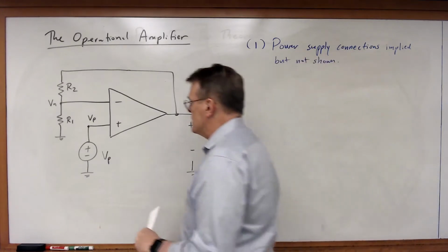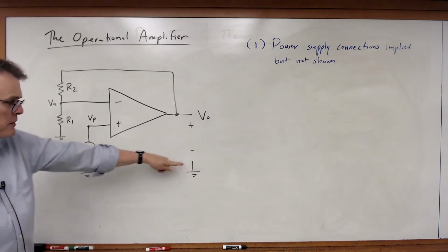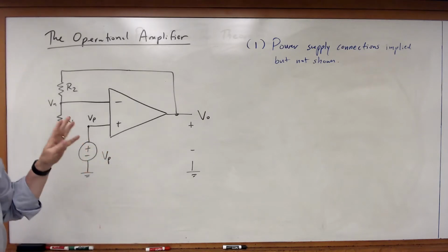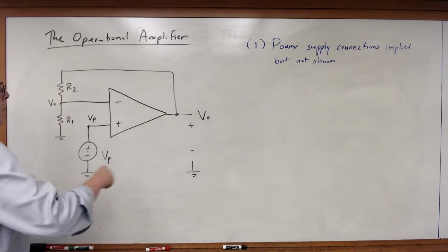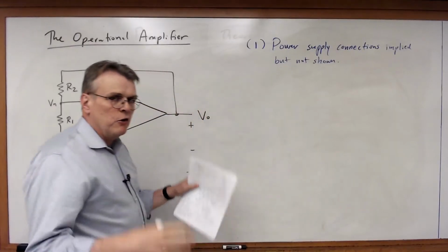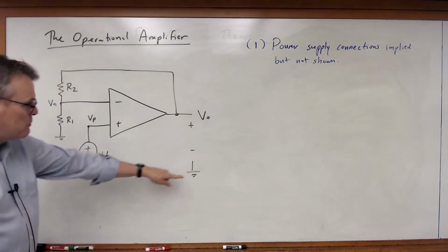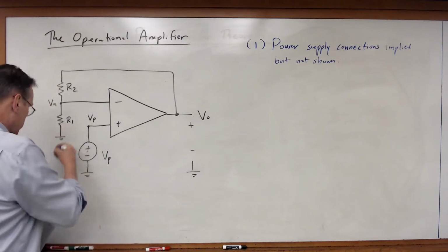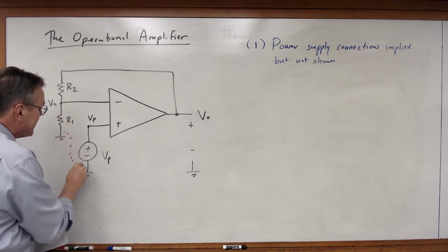Now the second thing is that I've got 3 ground terminals in this schematic. This is actually very typical for the way people will represent electronic circuits. What we're trying to do is avoid having to run a long ground wire over the entire schematic and hooking everything to that long ground wire. Instead, there will be multiple grounds throughout the circuit schematic because it's neater to draw it that way. But the implied assumption is always going to be that these grounds are all connected together.